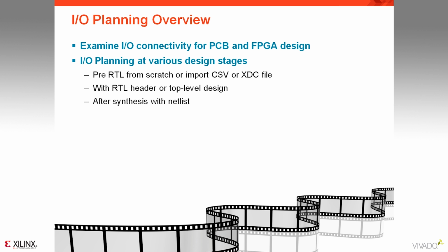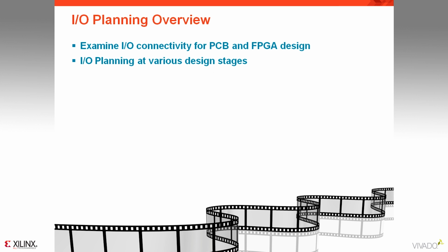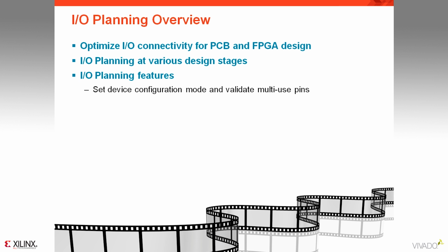Then you've got a netlist that's clock aware, and a lot more DRCs are available to allow you to interactively place the I/O ports DRC correct, as well as validate the final I/O pinout. Some of the other features allow you to define the device configuration mode and to validate your multi-use pins to make sure you don't have any conflicts. You can also define alternate devices. Sometimes designers are unsure what the actual final device will be for their design, and you can ensure that the pinout selected will work across multiple devices.